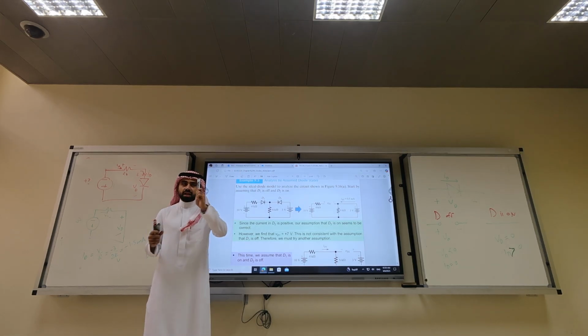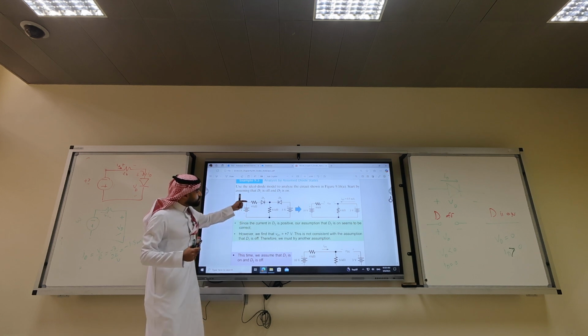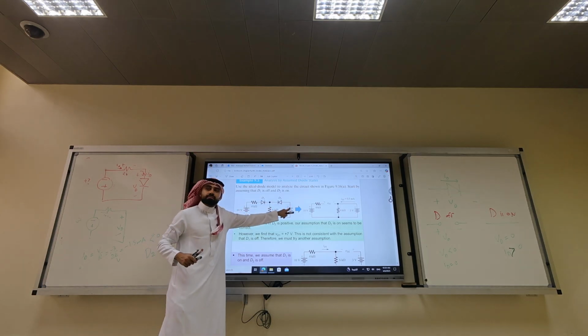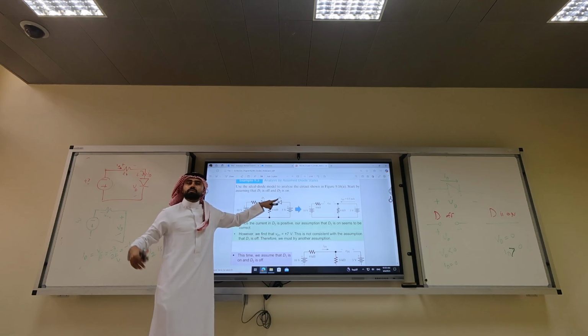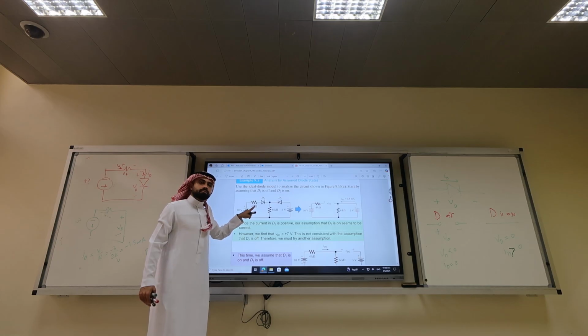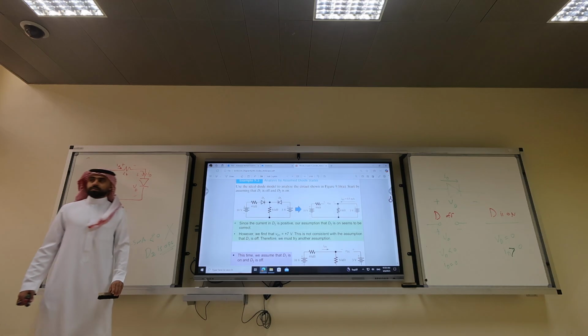So let's trust our analysis. The battery here is high, 10. Even if there is a voltage drop here, maybe it's 5, still higher than 3. Get it? So D2 should be off, D1 should be on. No need to waste time. Let's do it. Doctor, yes.